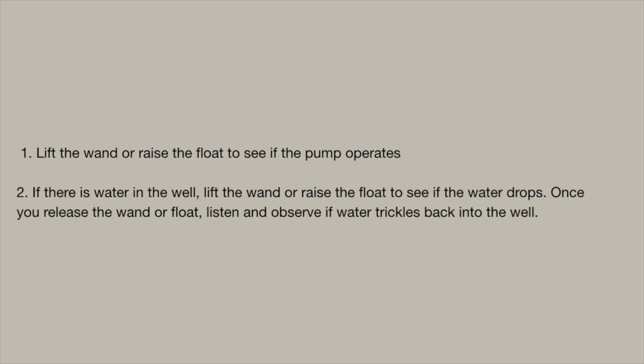Inspecting a sump pump. There are a few steps to inspecting the operation of a sump pump. 1. Lift the wand or raise the float to see if the pump operates. 2. If there is water in the well, lift the wand or raise the float to see if the water drops. Once you release the wand or float, listen and observe if water trickles back into the well.